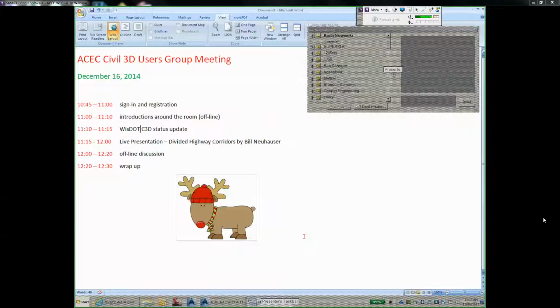It's obviously not the intended use of the super elevation controls, but it's a creative way of using the tools that we have available to help do complex things like slope transitions and some of the design model cleanup that would occur at the end of the design process.